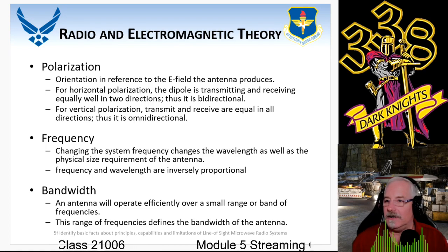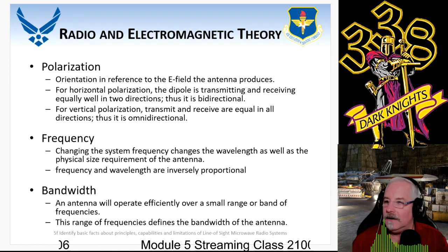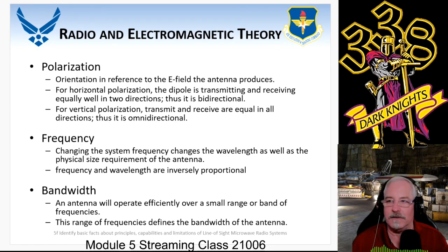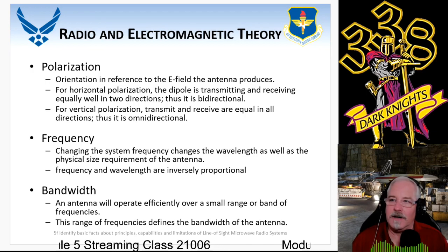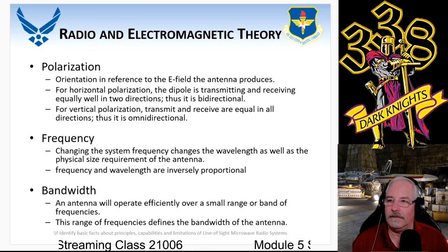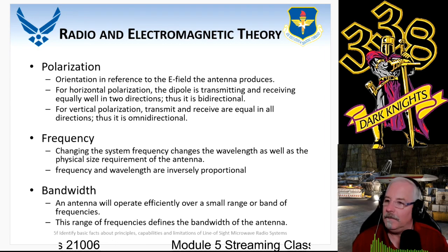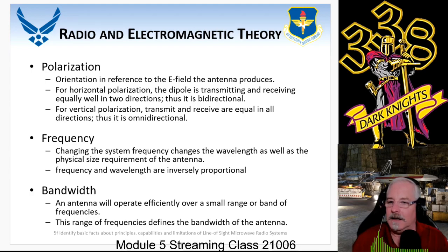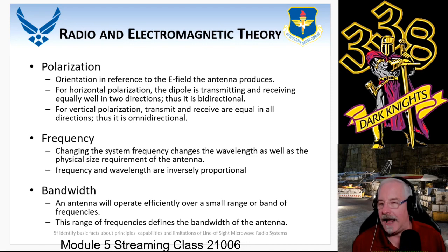We also look at polarization. Remember, the E field is what determines it. Linear versus non-linear: remember, you can talk between the two. You can't talk between two linear antennas that are opposite, in other words, a vertical to a horizontal. Frequency: always remember that every time you change frequency, you're changing the wavelength. Frequency and wavelength are inversely proportional. The higher the frequency, the smaller the wavelength. Bandwidth, of course, could be multiple things. This one is looking at the range of frequencies that the equipment can transmit. You can relate that to what is the data that you're doing.